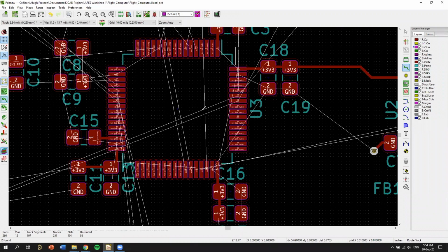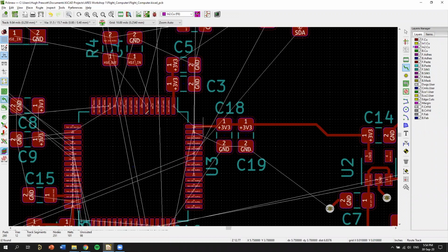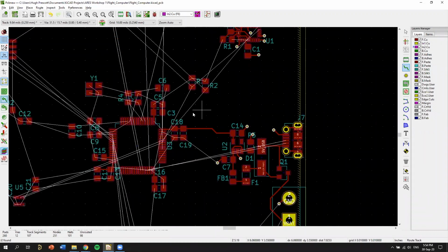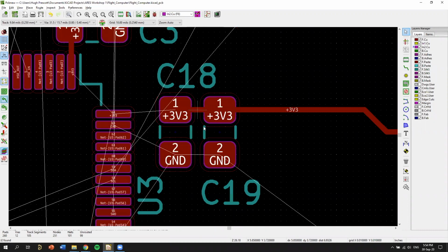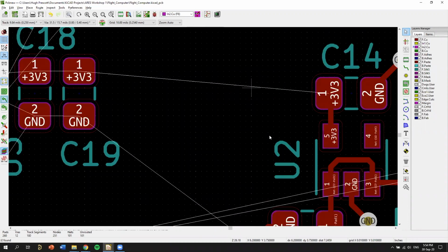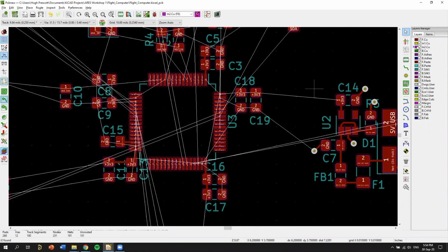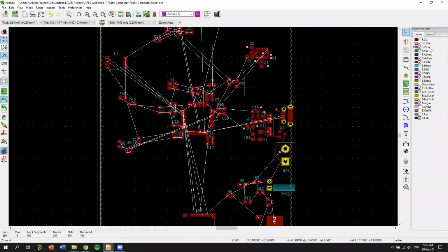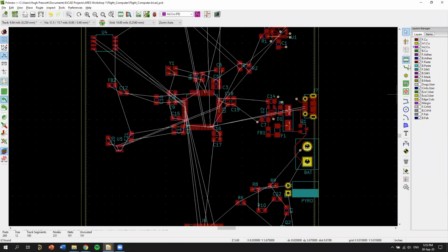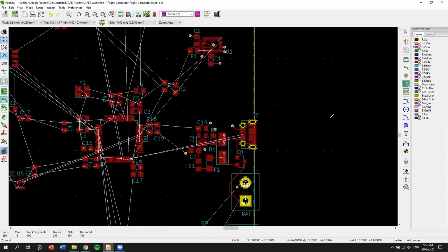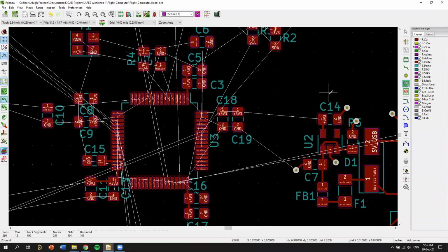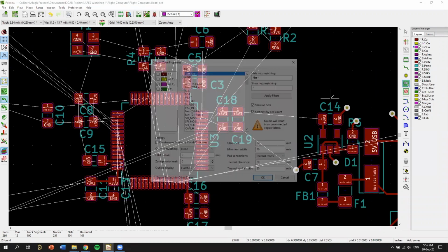And in fact, that sounds like such a good idea to me right now that before I finish today, I'm going to do exactly that. Yes. All right, so the plan is basically all of the things here are run off 3.3 volts. So why don't we, inner layer 2, let's drop a polygon. And essentially, this is where our 3.3 volts is coming out. Why don't we just have a pour that's kind of like, we want this to be 3.3 volts.